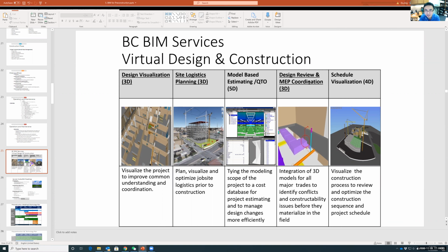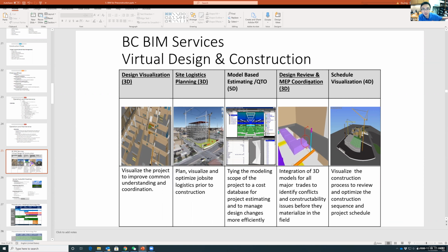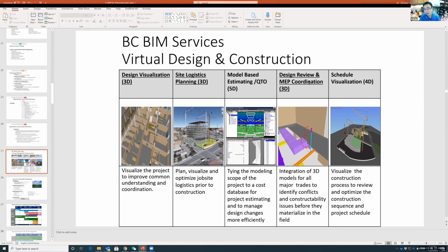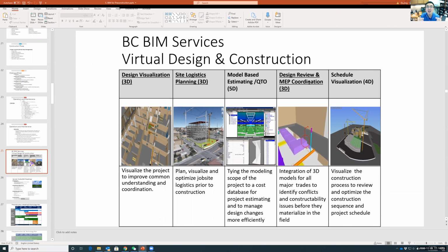So usually they are done by different parties, and it's so difficult for them to like each other. I think there's a psychological reason for that. Think about it. The architects are usually trained in design, for example, at UF, that's the DCP, the College of Design, Construction and Planning. But MEP people are a different group of students who are trained in a very different way, and the training, the methods, everything will be very different. And after you graduate, you go on very different career paths. Now you have to work on the same project. Usually people don't talk, and there's no contractual obligation for them to talk. That's why MEP is always an issue for clash detection. And I will give you more detail later.